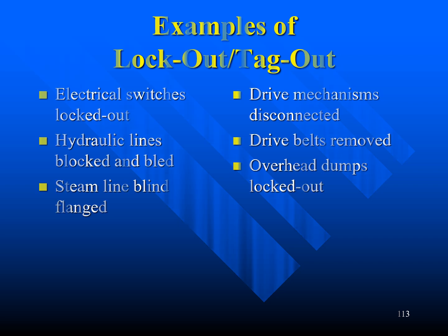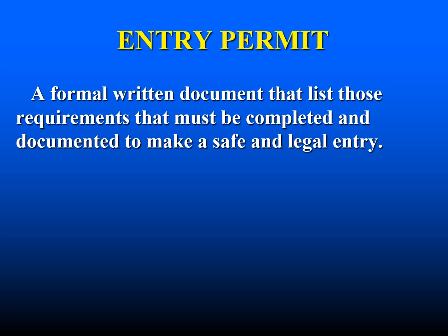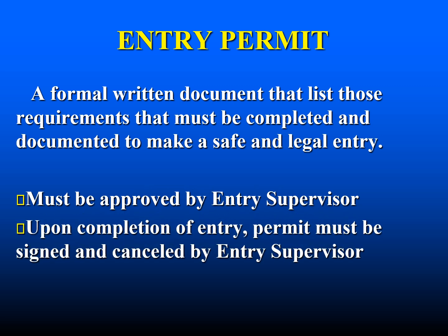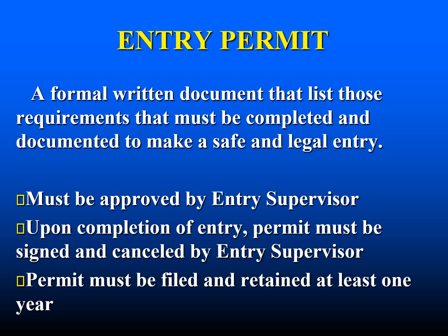Let's talk about an entry permit. An entry permit is a formal written document that lists those requirements that must be completed and documented to make a safe and legal entry. These entry permits must be approved by the entry supervisor, and upon completion of entry, the permit must be signed and canceled by the entry supervisor. The permit must be filed and retained for at least 1 year.